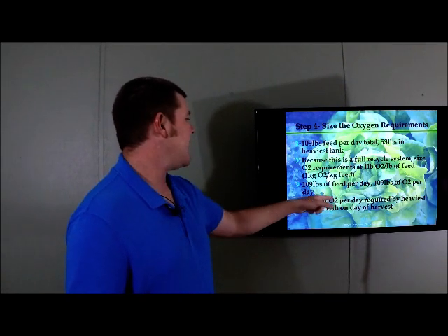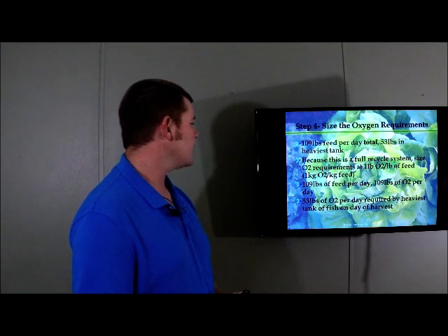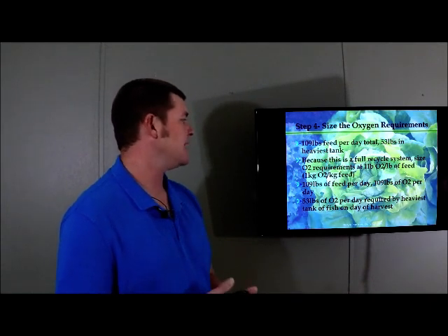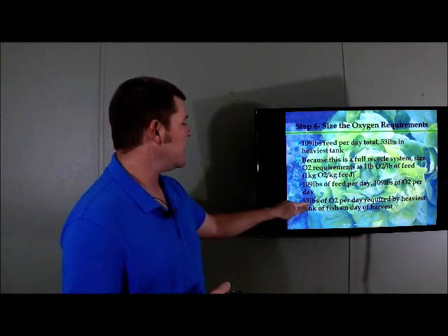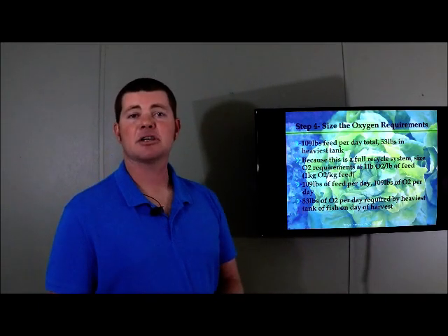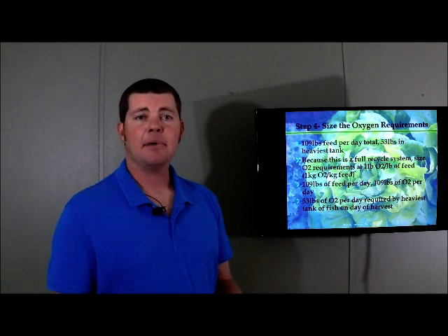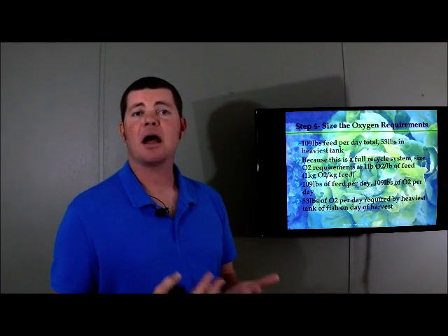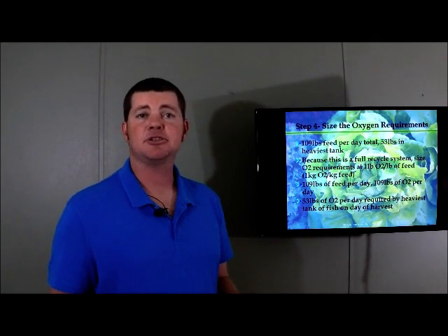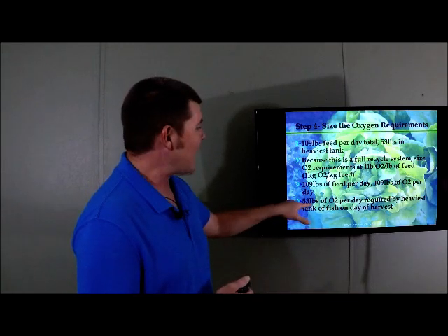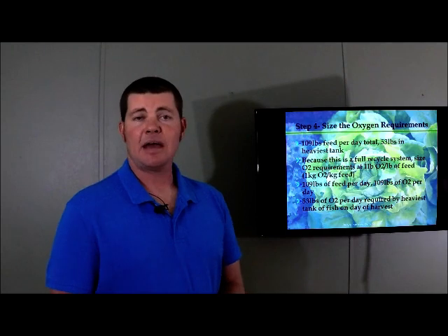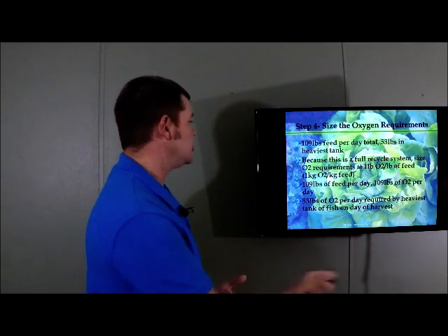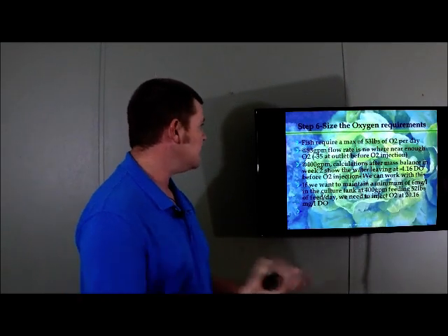Okay, it's 53 pounds of oxygen per day required by the heaviest tank of fish on the day of harvest. So for this example, we're not going to design every tank to require 53 pounds of oxygen at the same time. We're going to size our oxygen supply for the maximum amount needed at all 4 tanks at one time. So that will leave us with a more realistic oxygen volume need.